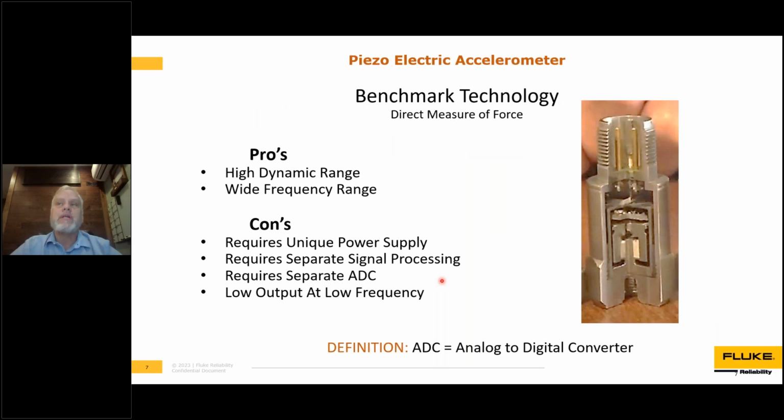A piezoelectric accelerometer, I'm going to talk about what I would call our benchmark technology here that we've used for decades in the vibration world. The pros of these devices: they have a very high dynamic range, almost matched by nothing that I'm aware of, in the ability to measure amplitudes at both very low and very high levels, oftentimes in the same device. They also have a very wide frequency range. And again, we're going to dive in a little bit on the frequency range of these devices.